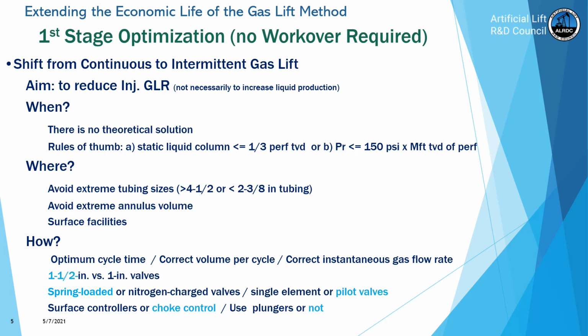Fallback losses are that portion of the initial liquid slug that is not produced to the surface because it's left behind. And we're usually talking about 5 to 6% of the initial slug per each 1,000 feet of depth of the point of injection.